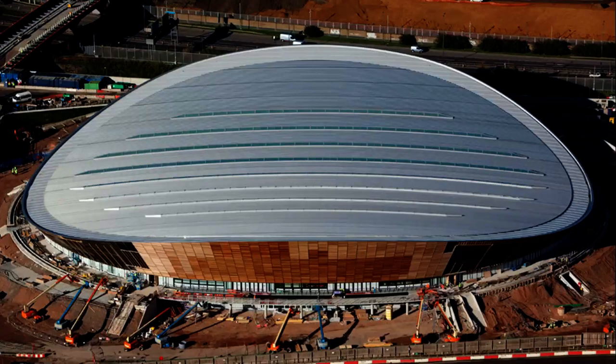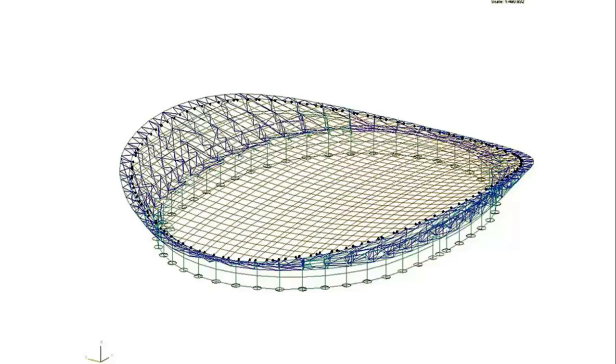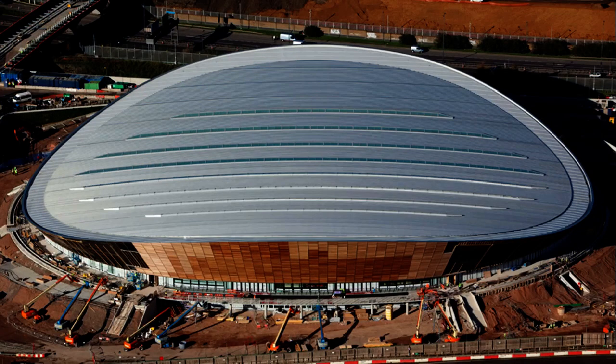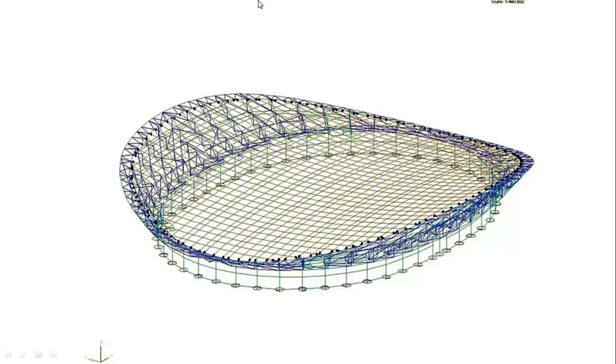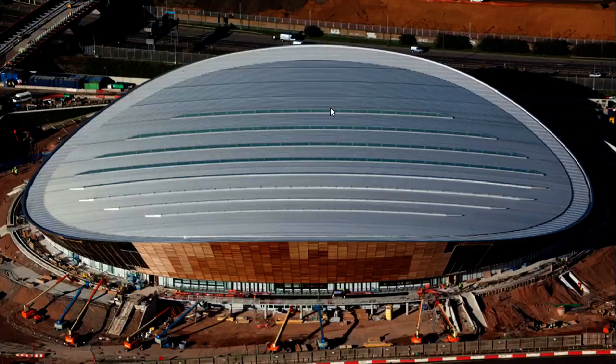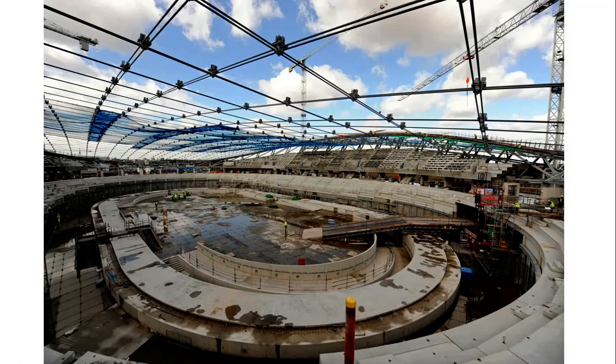It's not a thin concrete shell. It is actually wire. In this case the Pringles shape, this anticlastic shape, is developed by pulling on a huge trussed ring beam around the edge. The wire is being pulled from one direction that way and the other direction that way, and as you tension the wire in both directions, it naturally develops that overall Pringle shape. And there it is under construction, just to prove that I'm telling the truth.